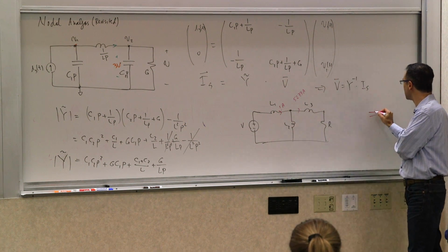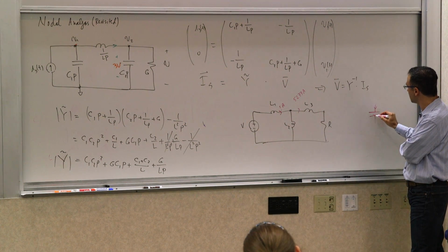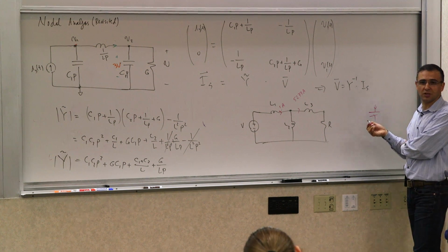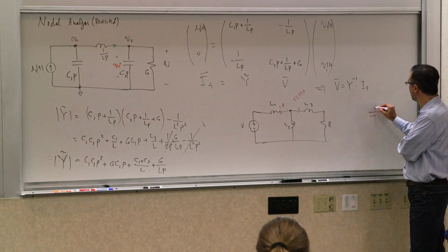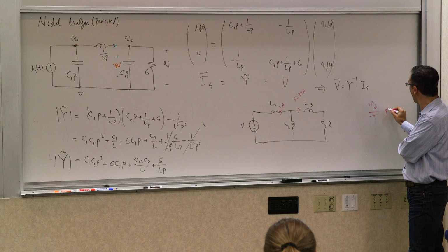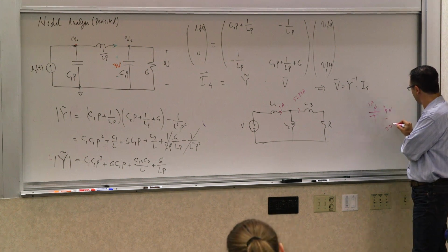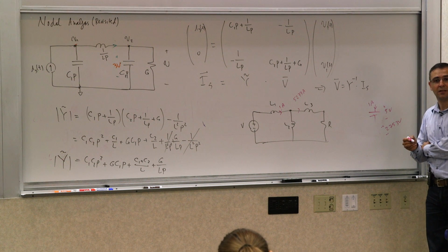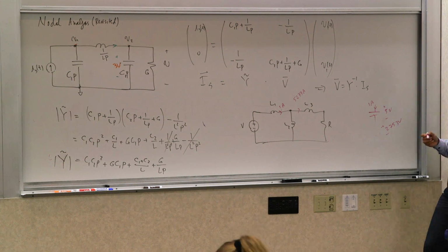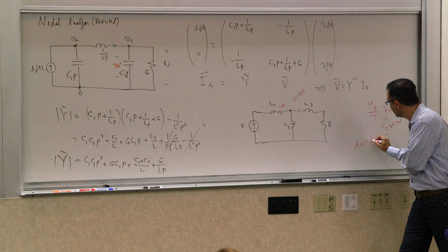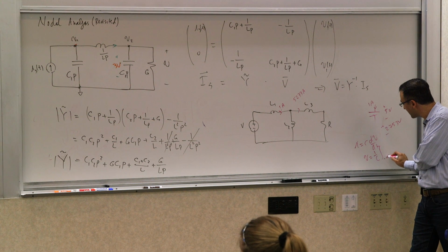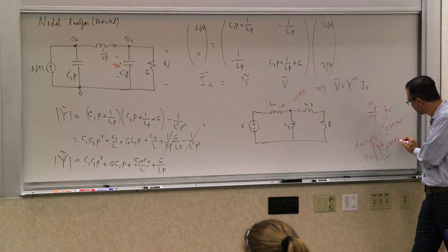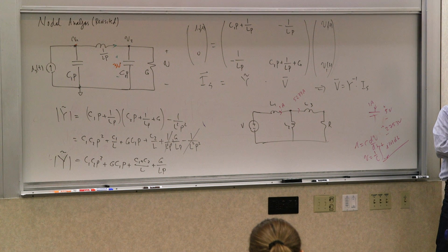The same thing for a capacitor, the opposite, right? If I tell you what the current through this capacitor is, I haven't told you what its voltage is. I've just told you what the rate of change of voltage is. If the current is 1 amp, this voltage at that instant could be 5 volts, it could be 2,753 volts, any arbitrary value. Because I is C dV/dt, which means that V depends not only on the instantaneous value of the current, but also all of its past history. That's the memory part of it.